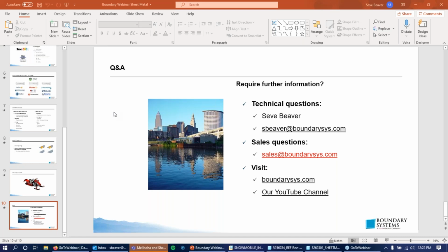That may be due to a strange feature that you've converted to sheet metal, or it may be due to an overlap like we encountered in my example. So it will not always work, and it'll tell you if it doesn't work. It'll tell you which features cannot be flattened. But as far as creating a flat pattern preview, you can always click that and try in Creo, and the engine will get that back to you if it sees it as possible.